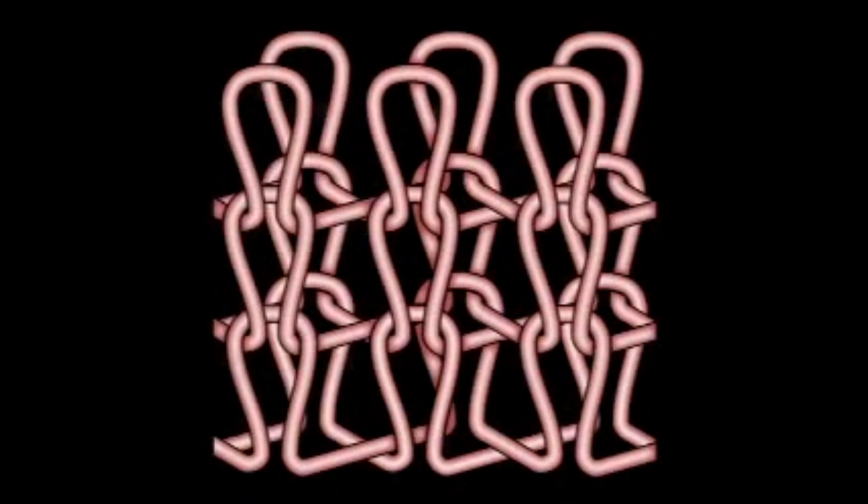Look at the resulting structure of an interlock fabric. Follow one course across different wales, and you will see a complex knit. Remember that 2 feeds are required for 1 course of knit. This first colored yarn knits on odd dial and even cylinder needles. The second colored yarn knits on odd cylinder and even dial needles. Because loops interlock and alternate from the front to the back, the structure of interlock fabric is much more rigid and stable than that of a rib. At closer inspection, you can see that interlock is the meshing or interlocking of 2 1x1 rib courses. This prevents adjacent wales from having mobility.